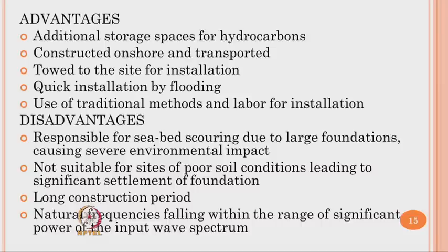These platforms have a very long construction period. The natural frequency of the platform falls within the range of significant power of the input wave spectrum, and that causes a lot of resonating response of these platforms, which could damage the platform.